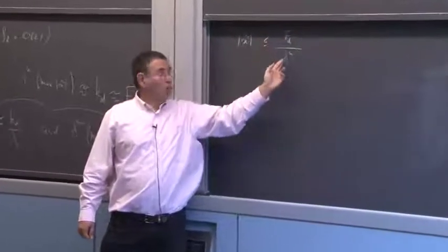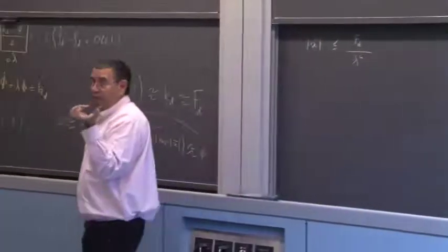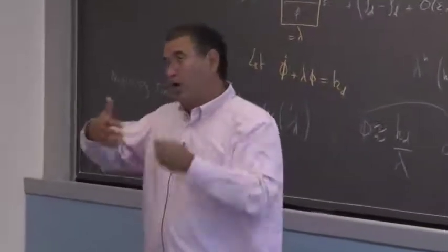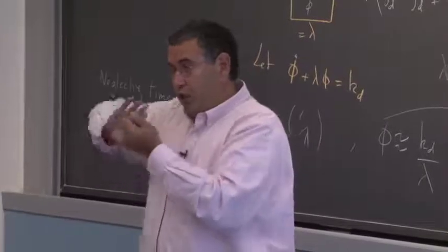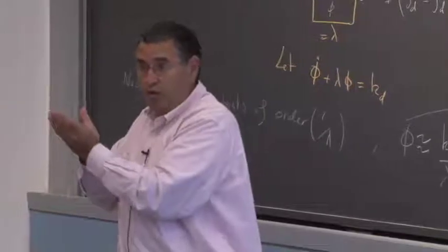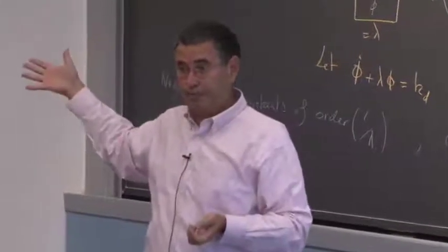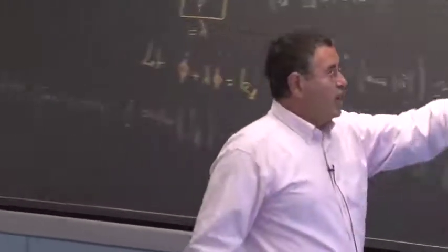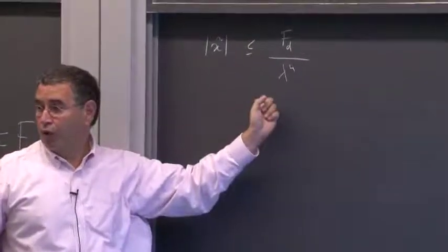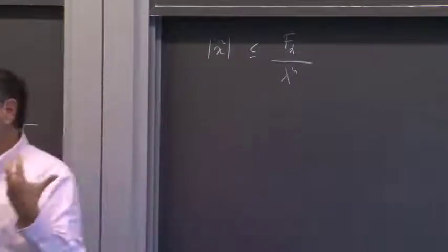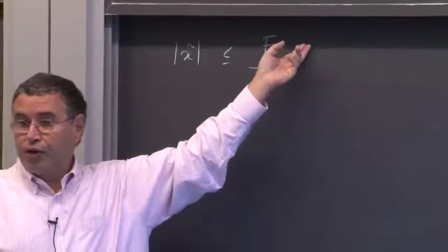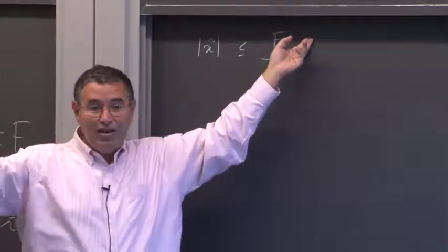What is the way to increase lambda? Well, it is to have faster unmodeled dynamics so that we can have a bigger lambda without interacting with them. So in a sense, this is a ratio between two forms of robustness, or two forms of model uncertainty. The top one is uncertainty on the parameters, the gains, additive terms.